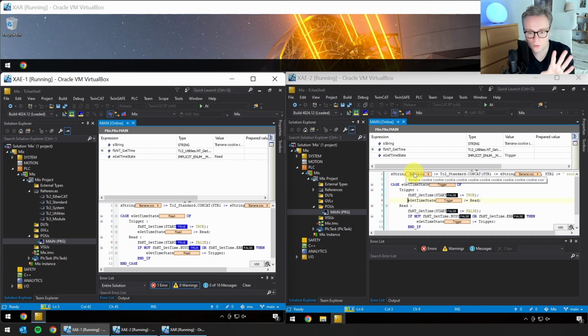And this is important, that you don't just do it with the TwinCAT software itself here, but also with any eventual functions that you had to download. So if you download the functions for Vision or for any of the communication stuff like TCP/IP, just store all those files aside as well, because you're going to need those when you rebuild the application if you need to. But that's everything I wanted to show in this programming session.